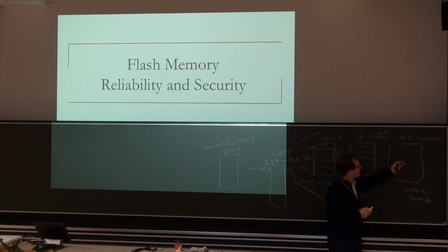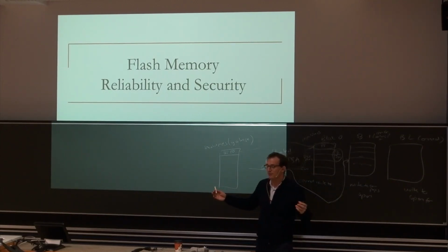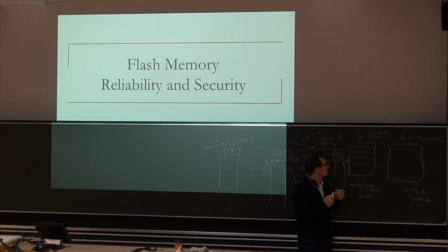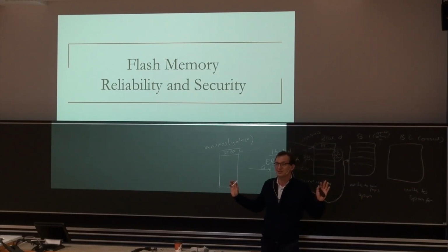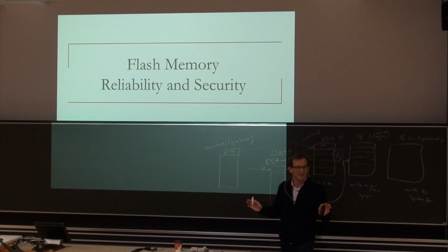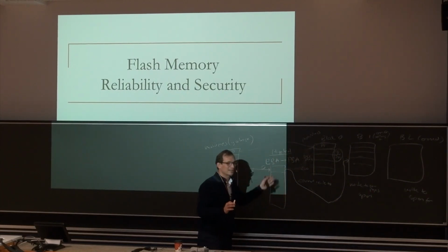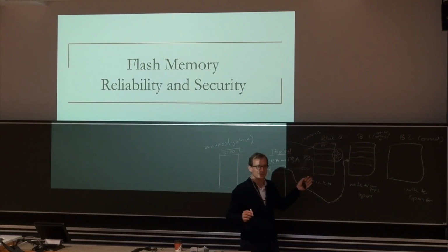And if you have a collection of pages that you know are not going to be written a lot, they're read-only, maybe you keep them in a single block. That way, that block is not going to be touched much for a long time. That's one trade-off. So that sounds good. Of course, it's not that simple because of other issues with the device, right? The device has another issue which is called wear out.